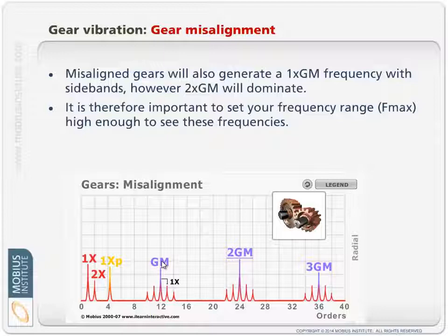But on the other hand, you have to be able to reverse that process. You need to look at the vibration and say, why is it so? Why am I seeing these changes? Why is the modulation changing? Why is the gear mesh changing? And go backwards. That's the truth in the case of analyzing gearboxes, but it's the truth no matter what you're doing with vibration.